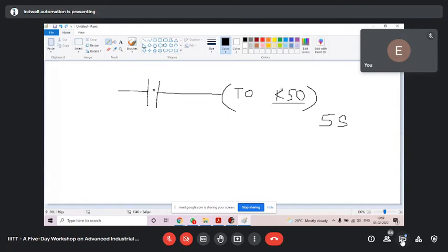If it is a fixed value on this preset location, this is the preset value location, on this location, if we have a fixed numerical value, we won't be able to change this from HMI. So if you have to change it from HMI, the requirement is you must have one variable address to this location, not a fixed value. Be very clear. We should have a variable address to this location where we have to change the numerical value from HMI, applicable for timer, counter, temperature, pressure, for anything. If you have to change a numerical value on any location, that location should be variable, not fixed.